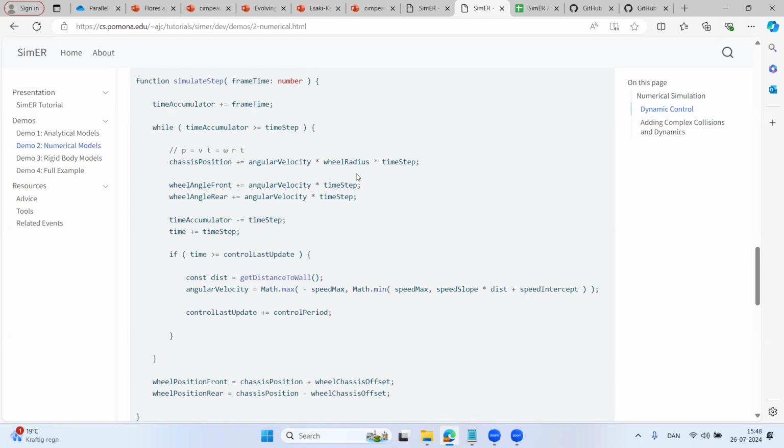That's because this simulation was extremely simple. There's no force, actually. This is just a constant acceleration. Actually, it's a constant velocity system. The second we put this thing on an incline and have gravity, or have external forces applied, external forces and not just external velocities, this, it's called Euler integration, will no longer work. It'll very quickly lead to errors. Then you can use something more complex, like an implicit integration or an explicit integration with multiple steps in between, where you're taking into account accelerations.